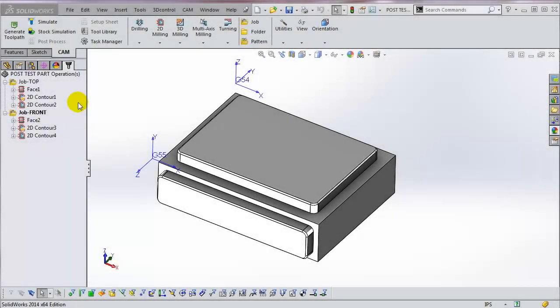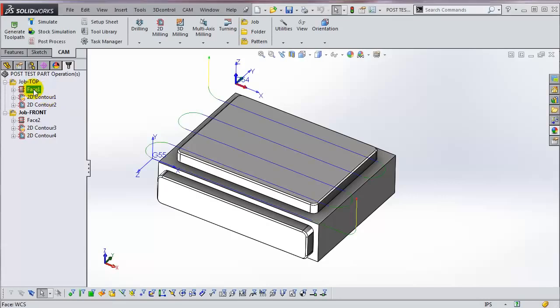A post processor acts like a kind of language translator. That is, it takes the toolpaths inside of HSMWorks, the positions, lines, arcs, and cutting parameters, and converts them into the specific codes and format for your machine and preferences.